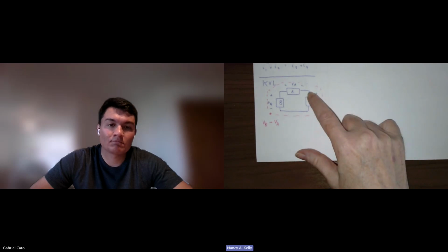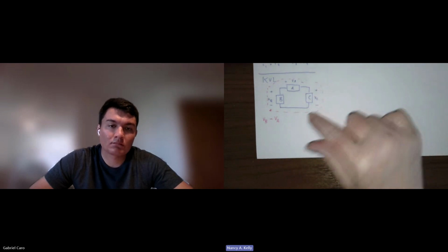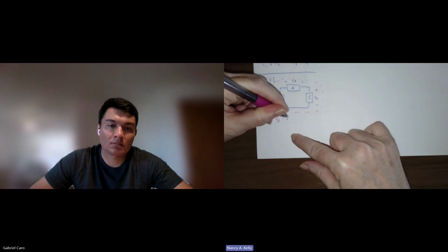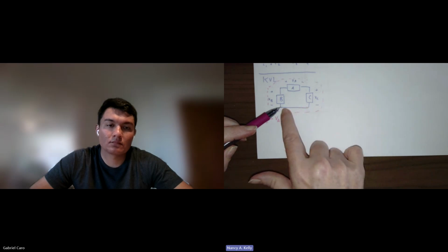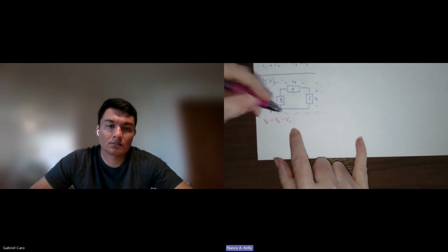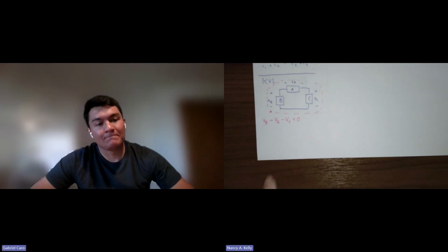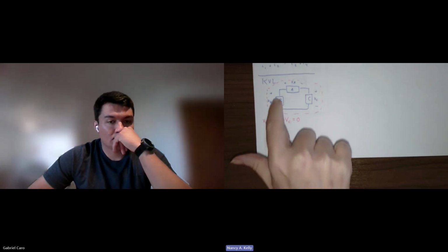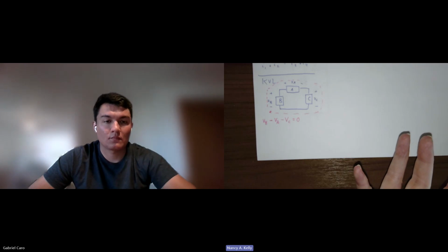And then when I get here, again, I'm entering the positive terminal, exiting the negative terminal. That's another drop, so I write that as VC. I get down here, then to get back to my starting point, I just go along this wire, but there's no voltage change there, so I'm done. Those are all the voltages, right? So that is the equation that describes the voltages around that path. And so if I know all but one, I can get the one I don't know, right?